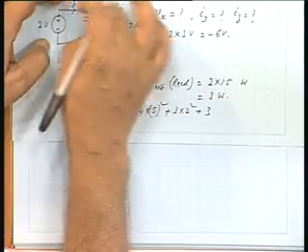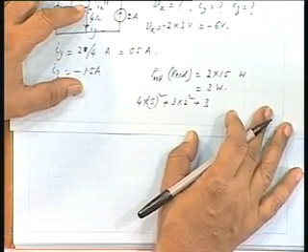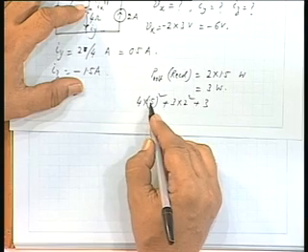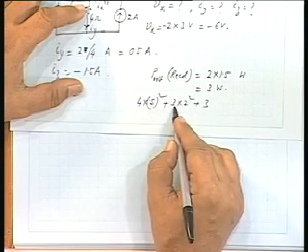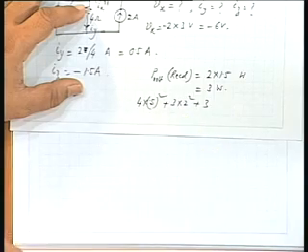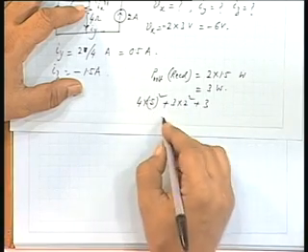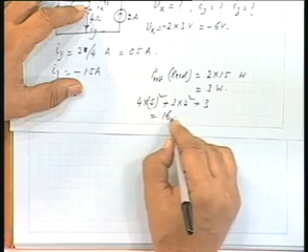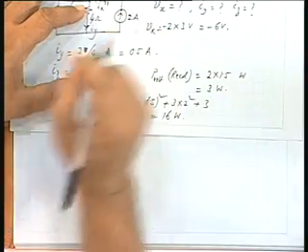So, the total power will be supplied by the current source. So, that works out to be, this is half squared, 1 watt, this is 4 into 3, is it not? 12 plus 3 plus 1. So, that gives me 16 watts. So, 16 watts of power will be supplied by the current source. Okay.